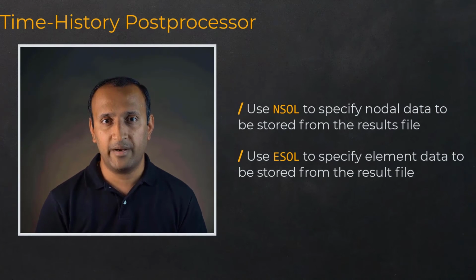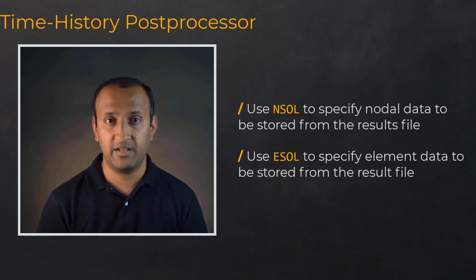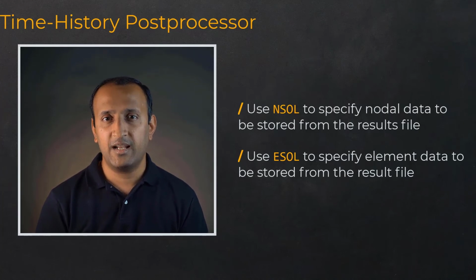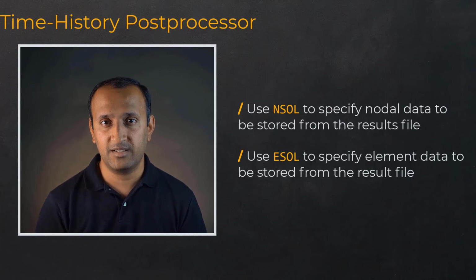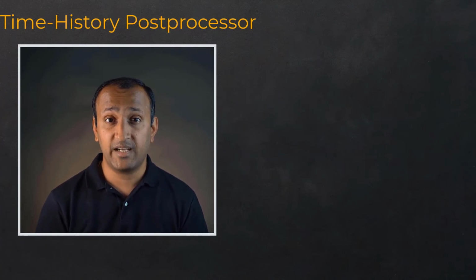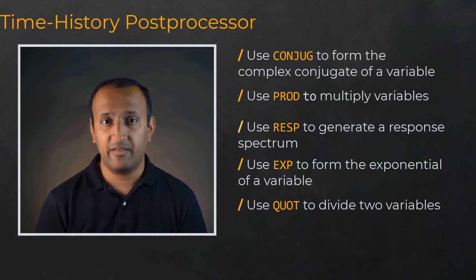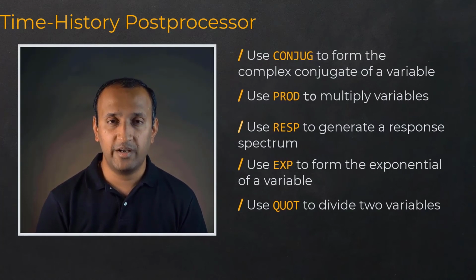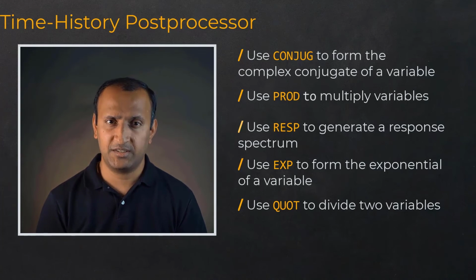NSOL and ESOL commands specify nodal and elemental data to be stored from the results file, respectively. Specific analysis data in the result file can often be processed to yield additional variable sets that provide valuable information. Some commands identify the variable and the format for the output, while others identify the variable data to be used to create the new variable. The actual calculations are performed by specific commands such as these.